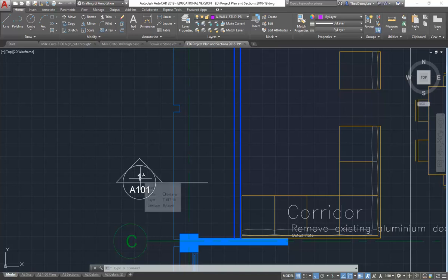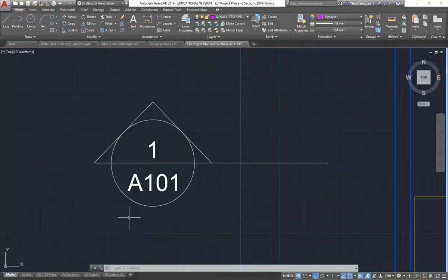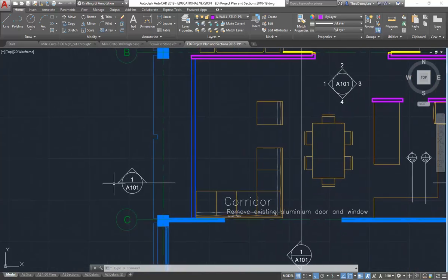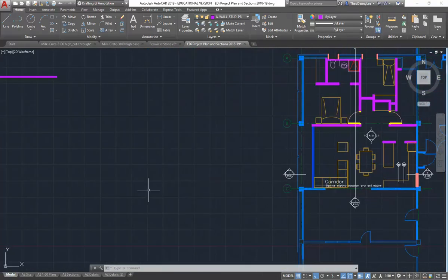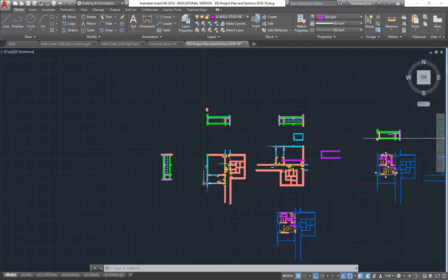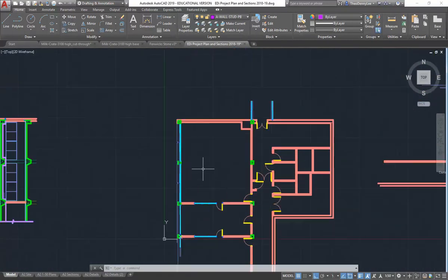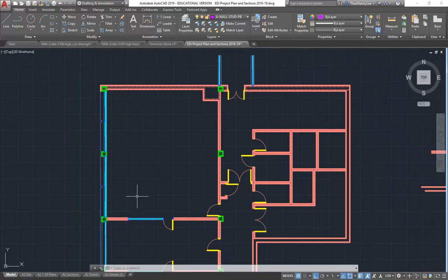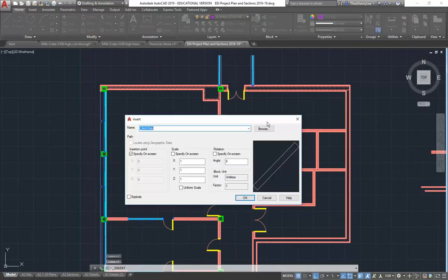But you can probably tell already here that I've actually just drawn circles and lines and text, because once you can draw comfortably in AutoCAD, you can knock things like that out in no time. It's just a circle with a few lines. So I don't mind how you do it, but if you again want to use the blocks in the AutoCAD library folder, I'll get those by going to Insert, More Options, Browse,